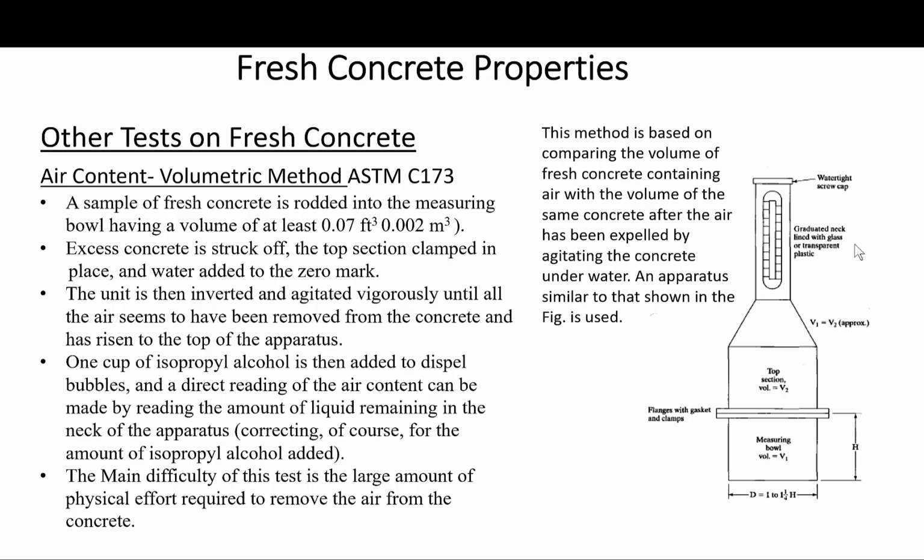The unit is then inverted and agitated vigorously until all the air seems to have been removed from the concrete and has risen to the top of the apparatus.